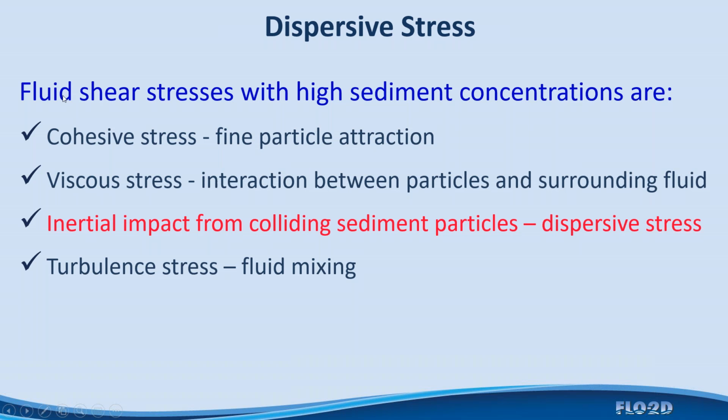The dispersive stress, well, first let me mention in a general sense that the fluid shear stresses in high concentrations of sediment flows have several components. One, the cohesive stress, which is really the fine particle interaction due to the clay, and the cohesive behavior of the clay as being a hydrophilic type of fluid matrix. That is, it likes water, and so the particle alignment and so forth will be such that it bonds the material together, and there's a cohesive stress that goes with this.